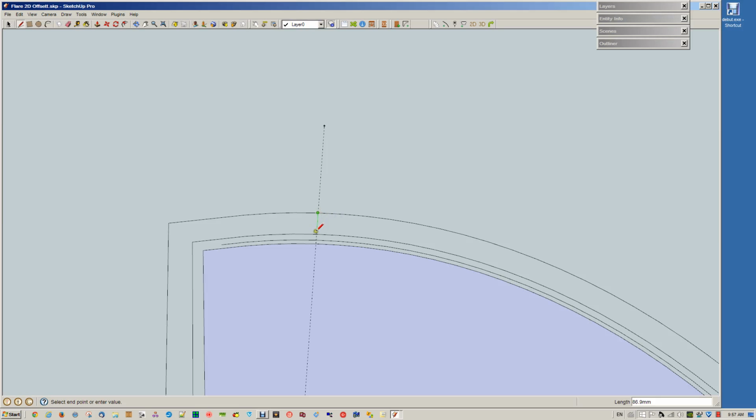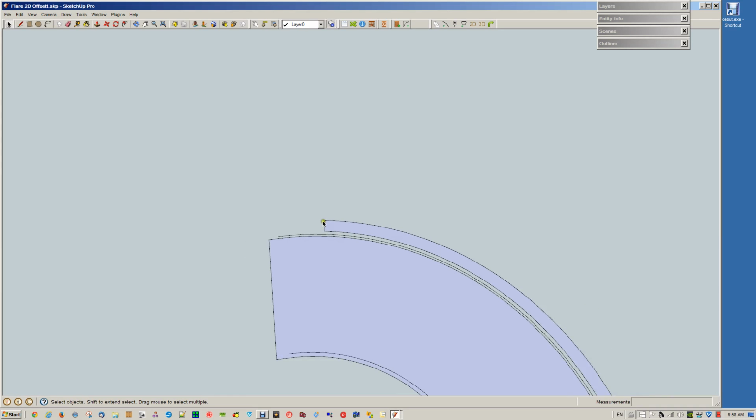So we're going to start off by finishing this. Delete these pieces. Join this temporarily. Triple click and delete. Clean that up. We also want to add 20 millimeters for the top riser. You can add what you want. I want to add 20. Now, at this point, we can get rid of our guide.